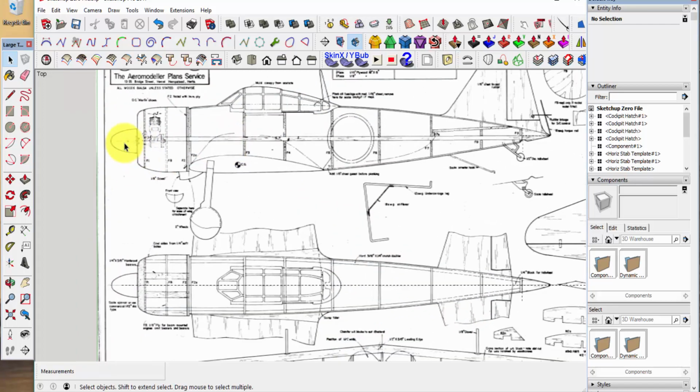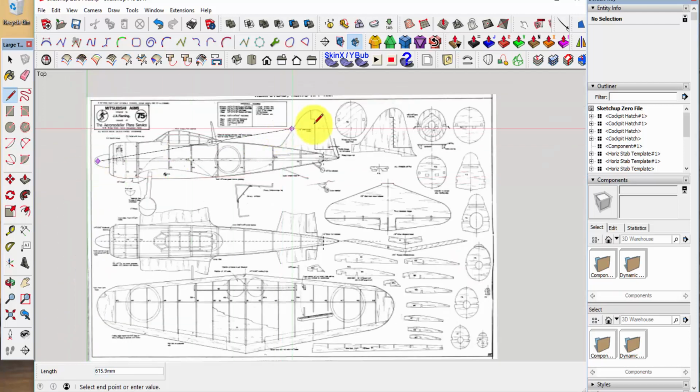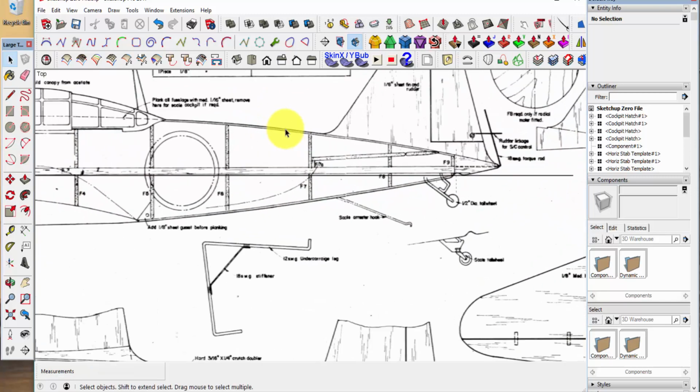We're going to come up here also, and we're going to create a datum line. And this datum line is very important, and we're going to again get on the thrust line of the model. We're going to take that back on the red axis. We're not paying any attention to what's drawn on the model now, other than that initial click on the thrust line. Okay, now we have another line, and we're going to do the exact same thing.